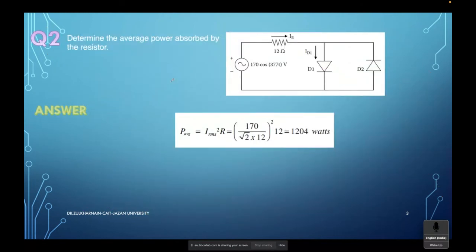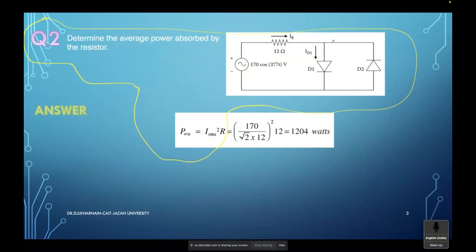Then all these questions, this is our only 2 marks question. Here he's asking you, you will get a circuit in the exam, the same one you will be getting. From this circuit, you have to get the values. The formula is easy. Here, the average power is equal to I RMS square into R. That is, current squared multiplied by resistance gives you the average power.